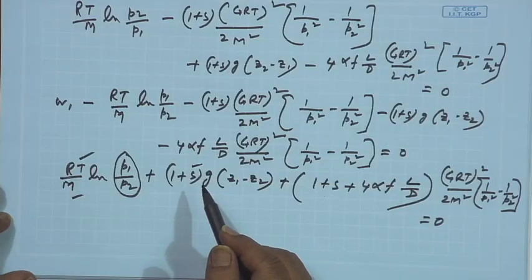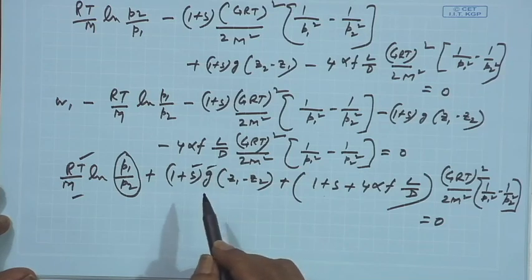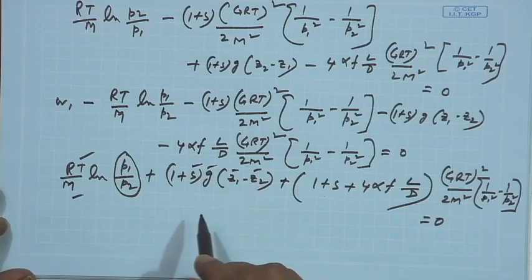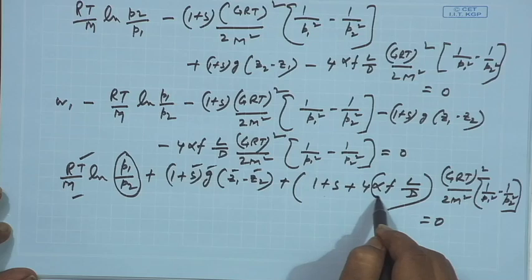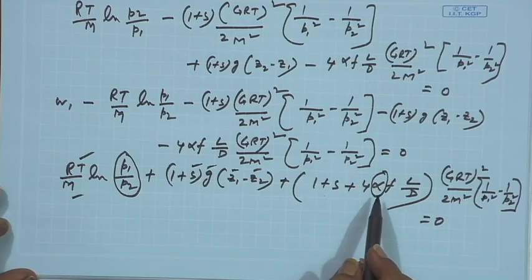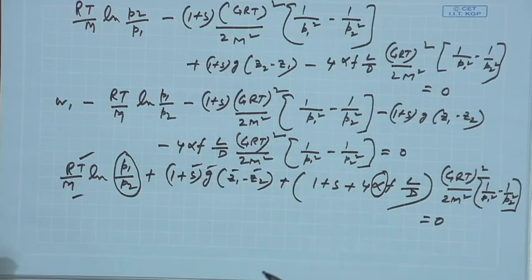So, if this is known, then only you can say, yes, I have come to know, and we can find out. Here, S, the quantity of the material being conveyed, is known, G from that place is known, and how much distance you are covering is known. One thing which can generally be unknown is alpha. We had taken df plus dfs to be alpha df, and subsequently that df we had substituted with the frictional loss, from the earlier equations where we found out the fanning friction factor.